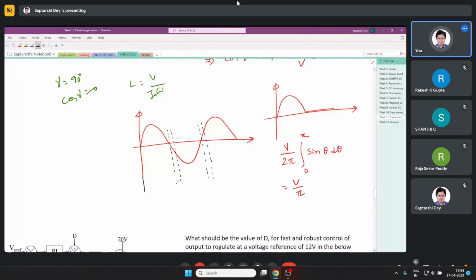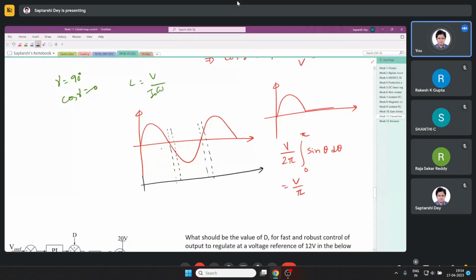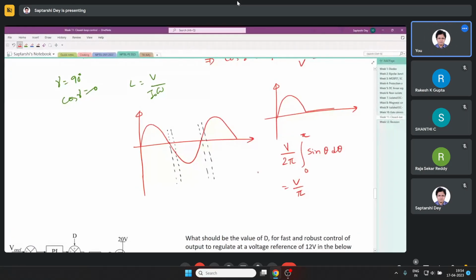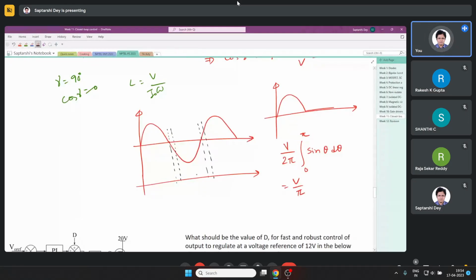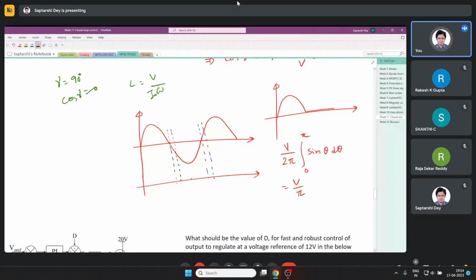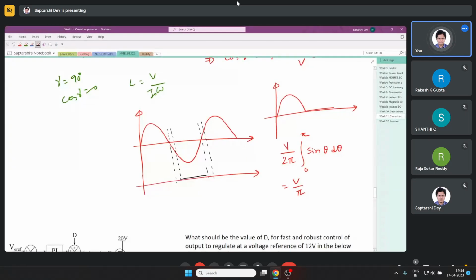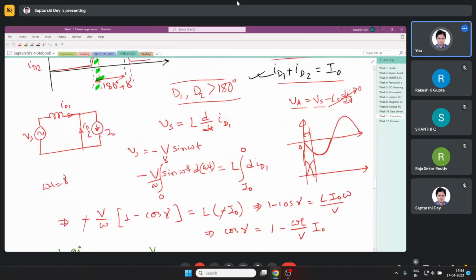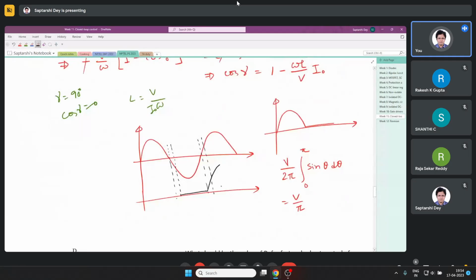Previously what would happen, sorry, I will draw it with some other color. The load voltage used to be, say I'm drawing from here, 0 until here, then it would start following the source voltage. Now since the commutation is going on, this circuit condition means the load is still short circuited, means the load voltage is not increasing here.